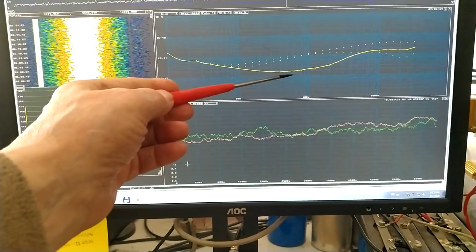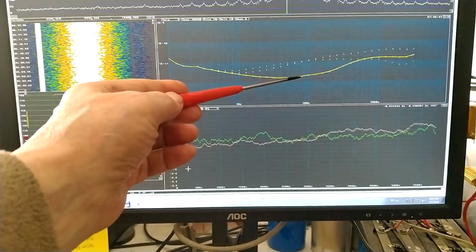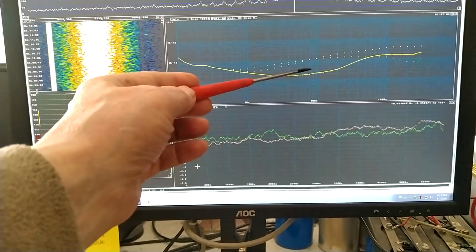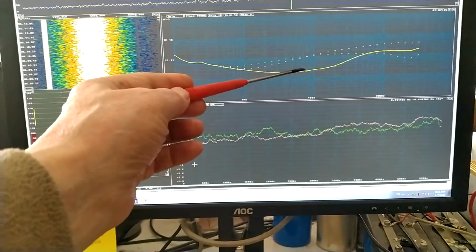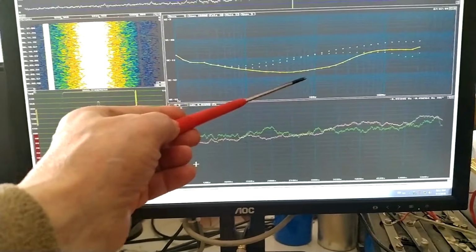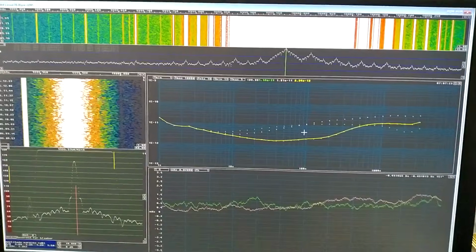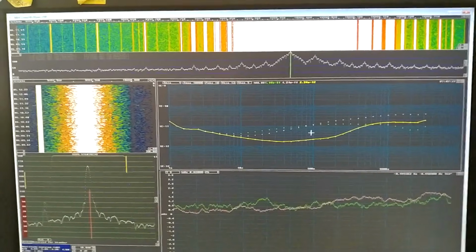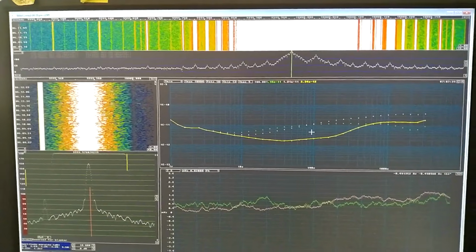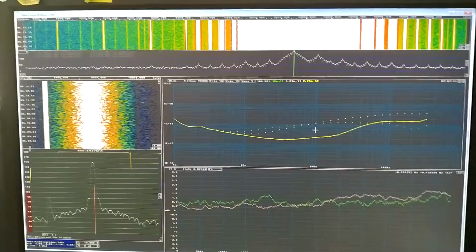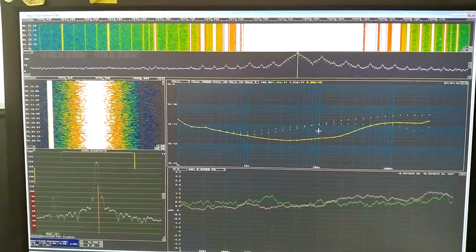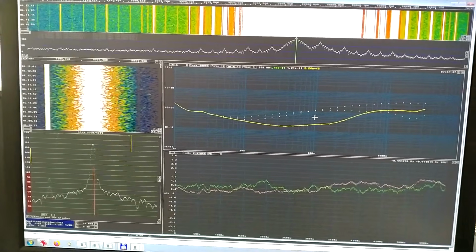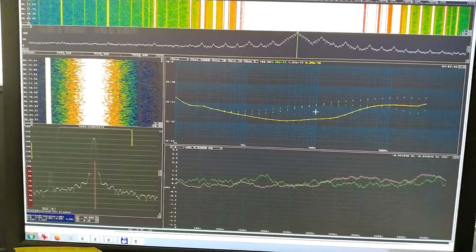The yellow trace is the correlated, which is the measure of the device under test, that is the rubidium source. It comes out as 2 times 10 to minus 12 at 100 seconds, 2.24. And that is reasonable for rubidium sources.